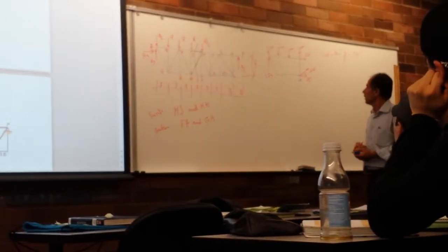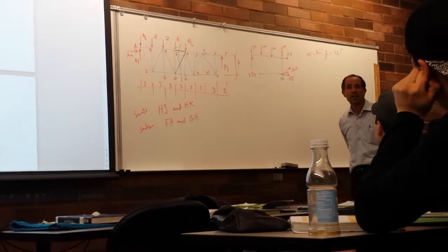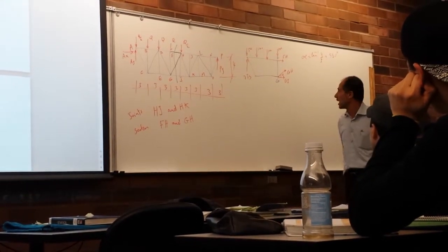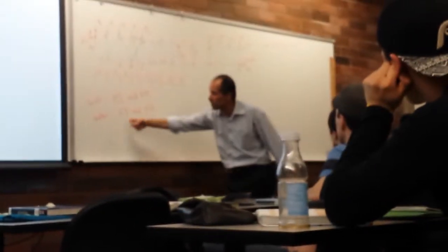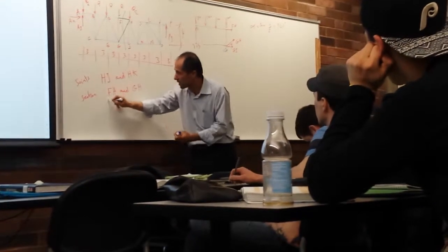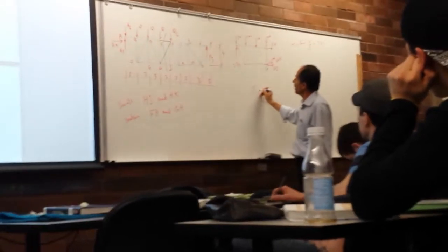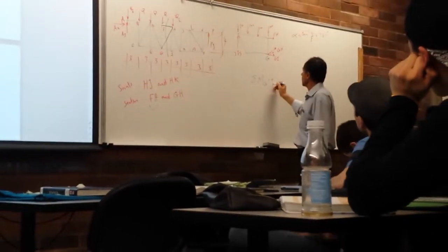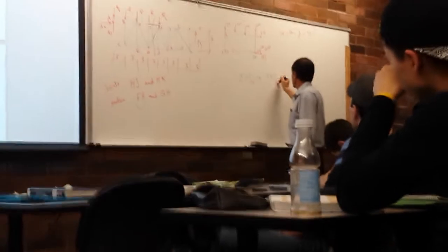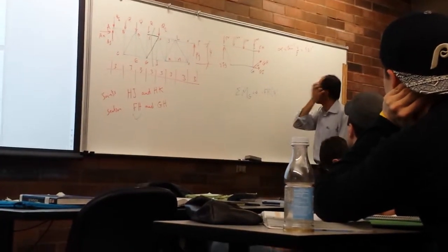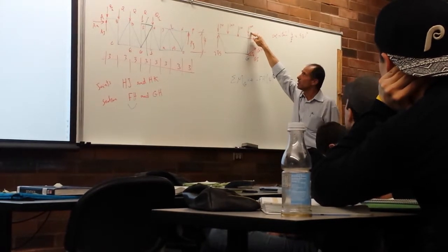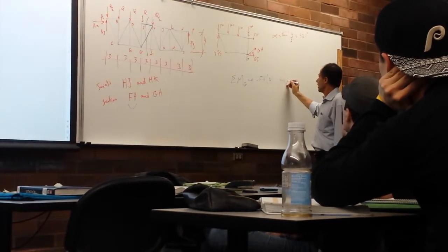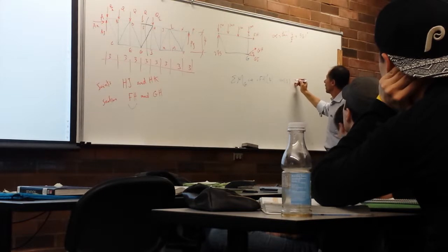To get your FH, what is the best way to start? Sum of the moment at G. I get FH because I'm looking for this one. So we'll start with this. Sum of moments at G equals 0. FH times 4 is negative. Agree? This 100 is not going to create a moment. The 100 times 3 is negative, another 100 times 6 is negative.